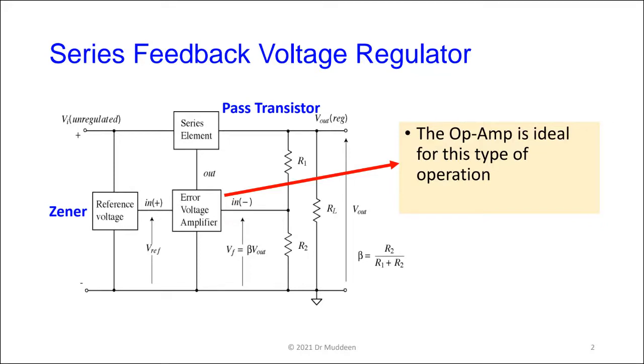The first version, which we discussed yesterday, was created using a single transistor. One input goes onto the transistor's emitter, which is the reference voltage. The other input goes into the transistor's base. The collector voltage fluctuates depending on what happens with our regulated output voltage, so as the output went up and down, the error amplifier gave the opposite reaction.